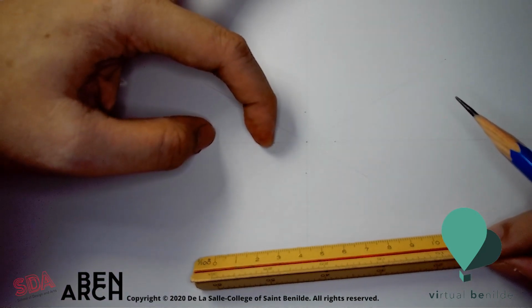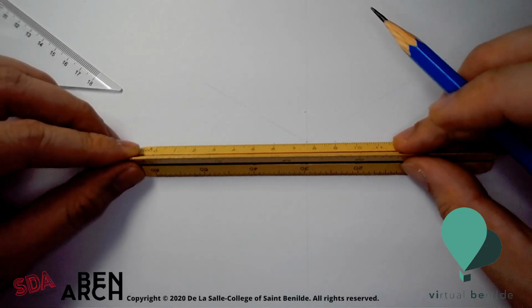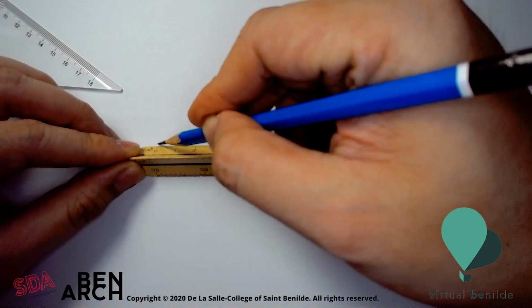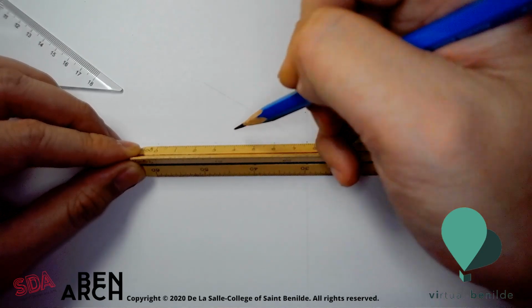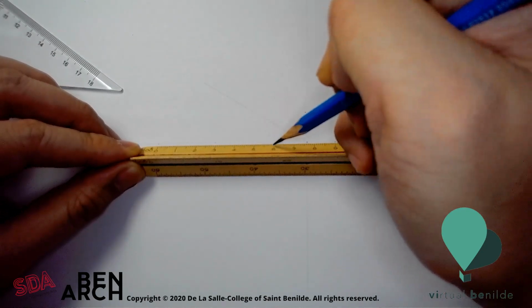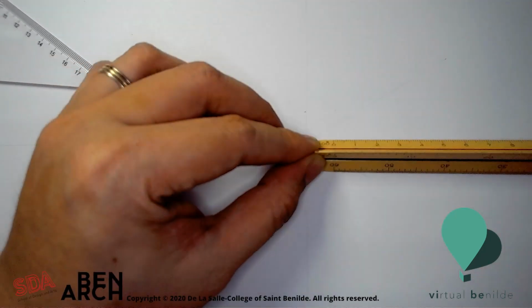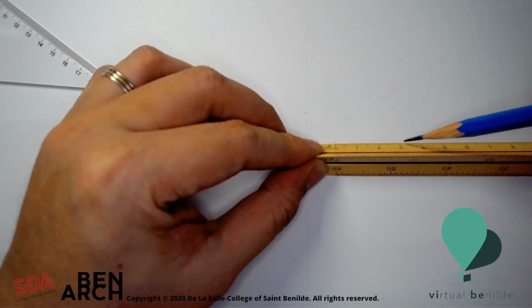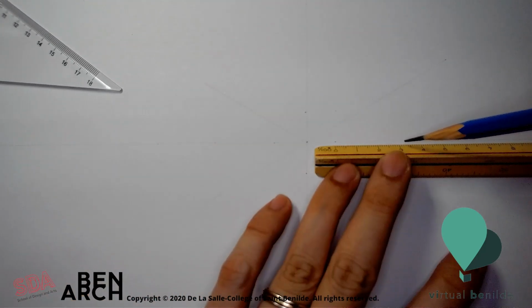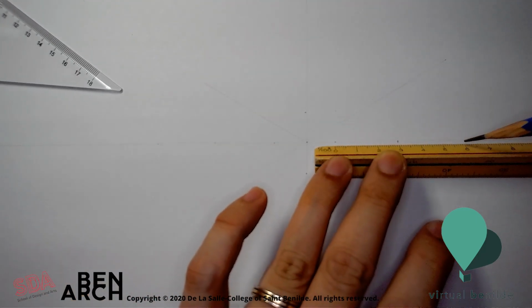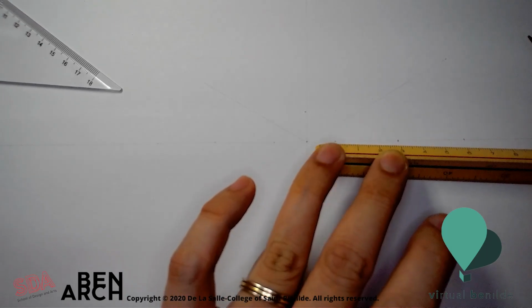So this distance is going to be the void. So therefore, the object, which is the left elevation, is going to be somewhere here, exactly 3 meters, and another void where this is 3 meters of void. Here, we take that same thing. First, the void from the front elevation. It's going to be where it is. So I'm going to mark up 3 meters, another 3 meters is where the 6 meter is.